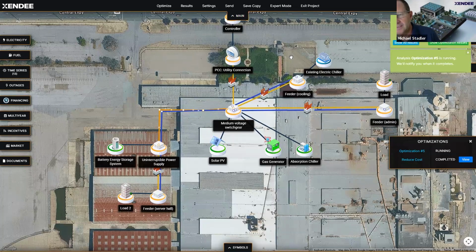Maybe we want to also answer one of the questions. Should the DERs and other components at critical locations be used for loss considerations? You can add to this, but in terms of the locations, the exact locations determine the length between certain nodes. So yes, if you have the exact locations, then we can calculate the exact length, which will determine the losses.